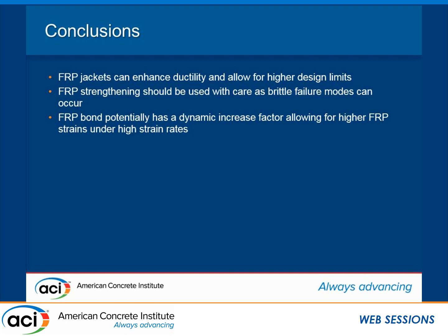Now, taking the same equation and then modifying the properties of steel into FRP and applying that to the surface, and I've done this a few years ago, but basically you can say for a level of seismic ductility demand, you need X thick material given your FRP has this property. That's based on displacement. It's like adding stirrups. Yeah, it's a performance-based design based on the concept that you want to gain a ductility of, say, 4, then you can go back and calculate the area of the reinforcement that you need to do that.